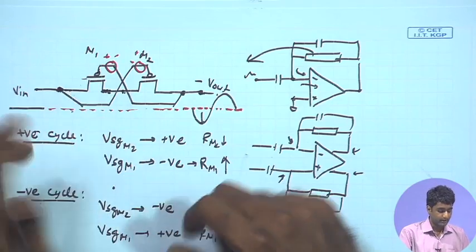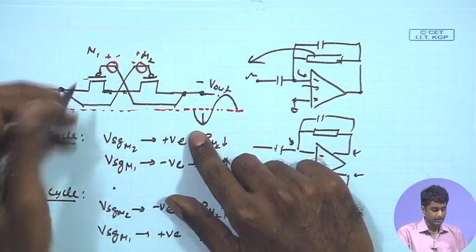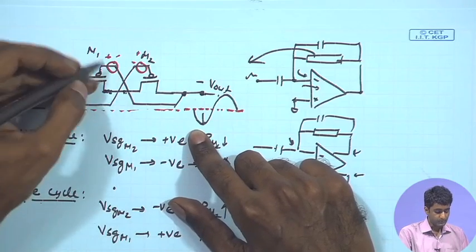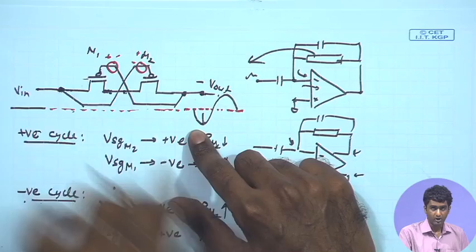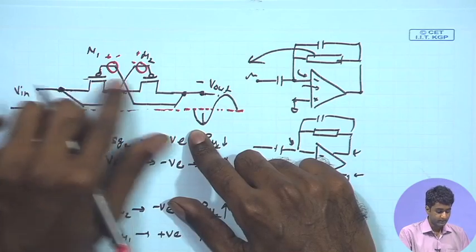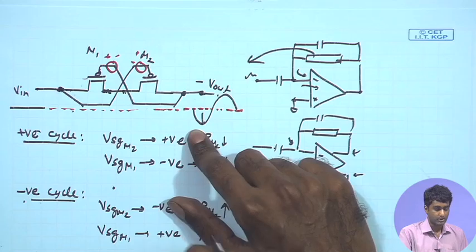So, basically if I insert an additional voltage over here such that the transistor staying off has an additional VSG drop, that can help us in reducing the overall resistance across the switch.